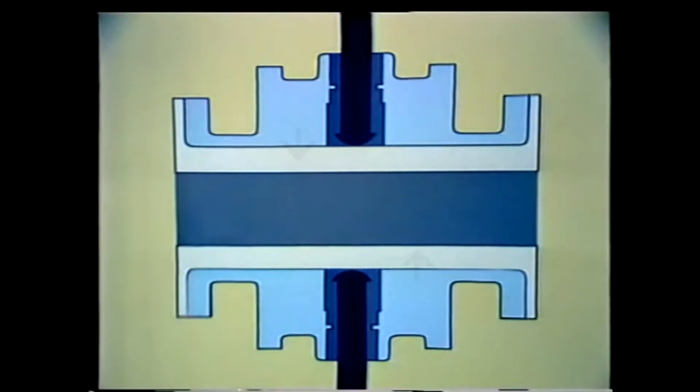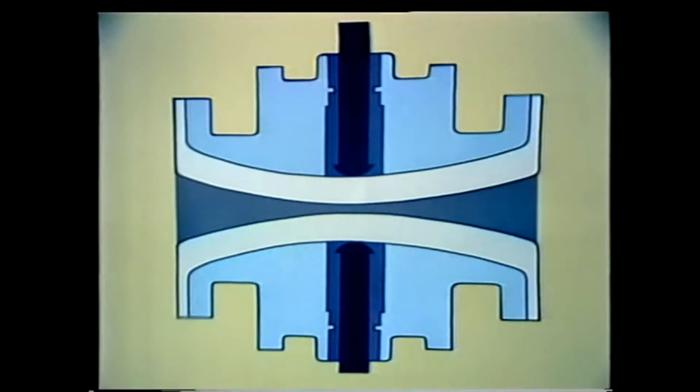Now, the boot valve is another variation of the basic diaphragm valve, and it is similar to the pinch valve. Like the pinch valve, the boot valve has a smooth, flexible tube running through it. There are two compressors that flex the boot to start, stop, and provide throttling action. The boot valve also has good throttling characteristics and is used for the same basic purposes as the pinch valve. With a double compressor, the valve can be shut quickly to stop flow, with each side of the boot flexing to close the valve. Wear on each is reduced by half. That gives the valve added life.